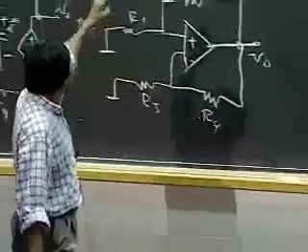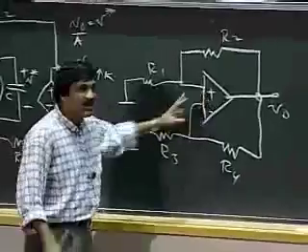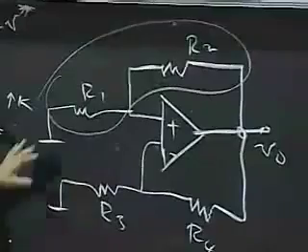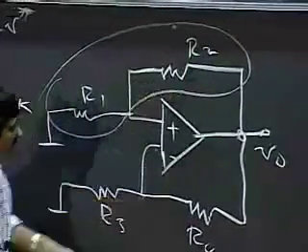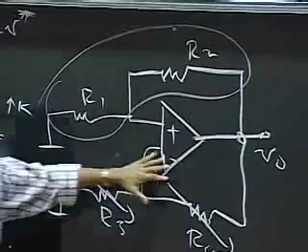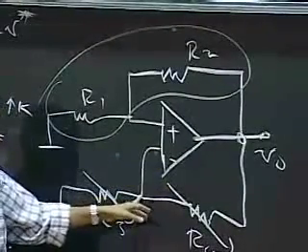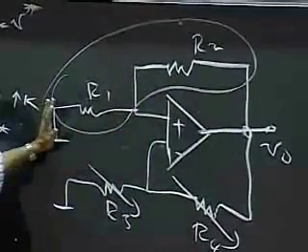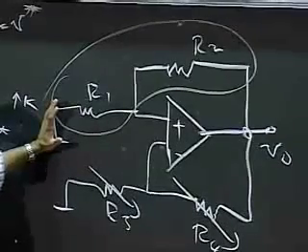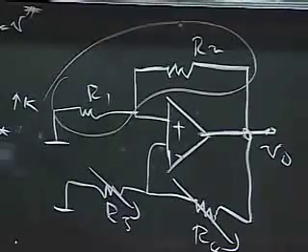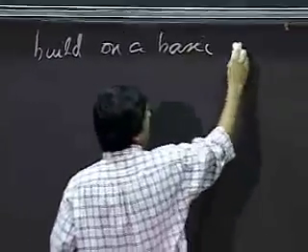So what we'll do is look at the op-amp circuit and focus on the situation where I have net positive feedback. In particular, just look at this circuit with R1 and R2 sent both to infinity, so I have no negative feedback, and I ground this terminal here. Let's take a look at what happens to a circuit with positive feedback and see if I can build some interesting circuits. We'll build on a circuit called the basic comparator.